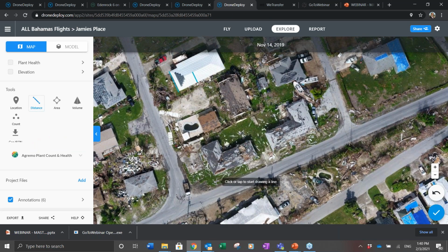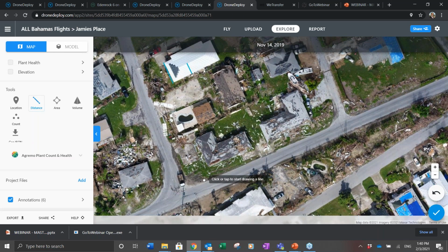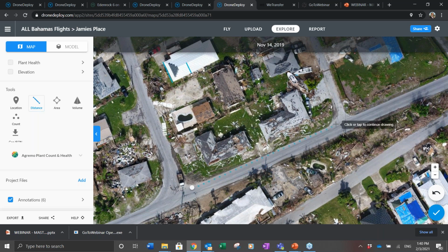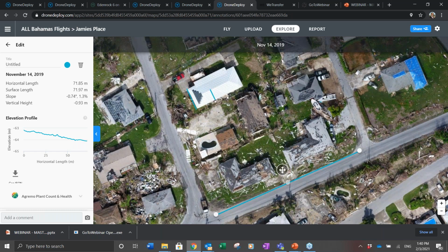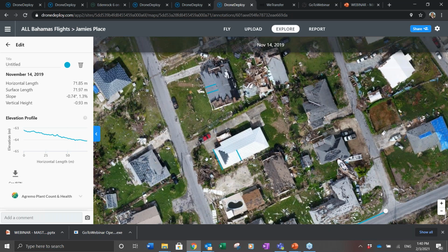How's the accuracy of these dimensions, Darren? Yeah, on this map, without putting in what are called tie points, or where we use robotic total stations, you're within plus or minus probably 10 to 20 centimeters. So it's not survey grade. For that level, we would have to include tie points and GPS, robotic total stations, ground control points. But for quick information and data that's required, this is certainly sufficient.